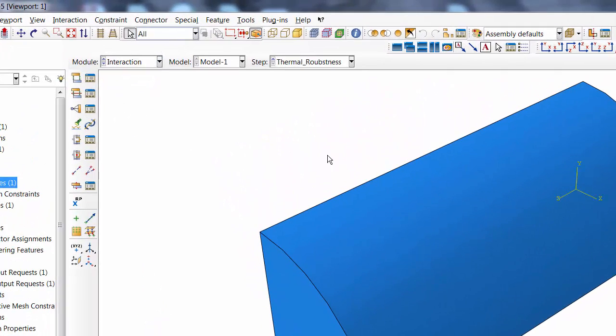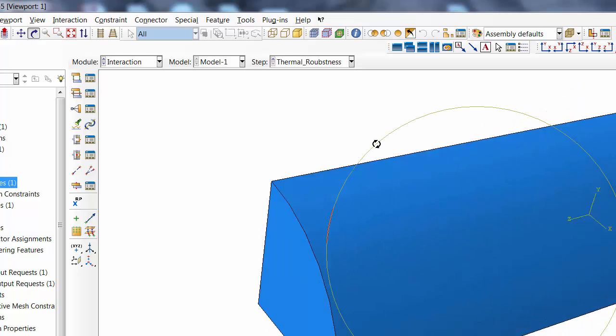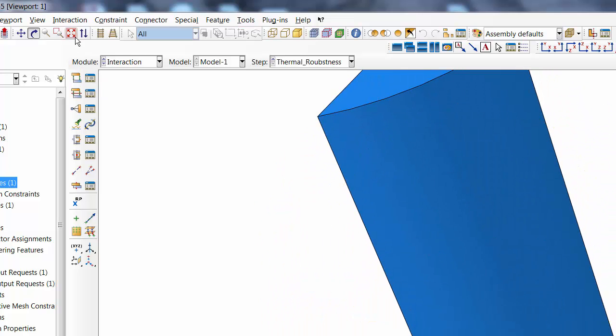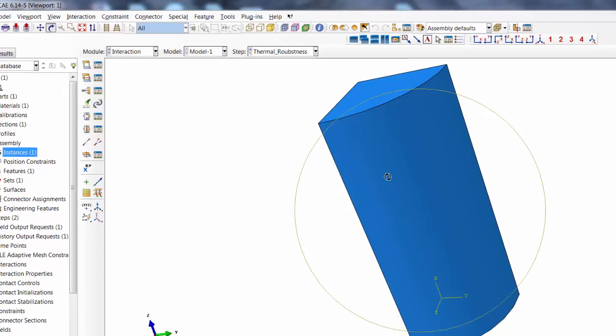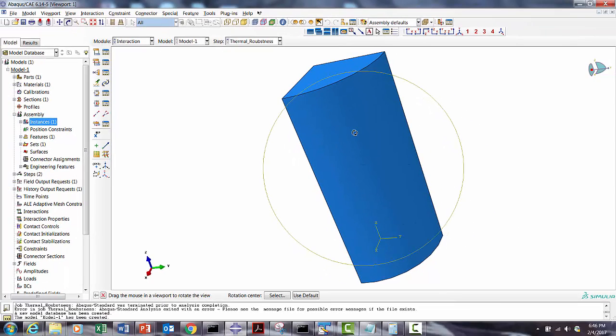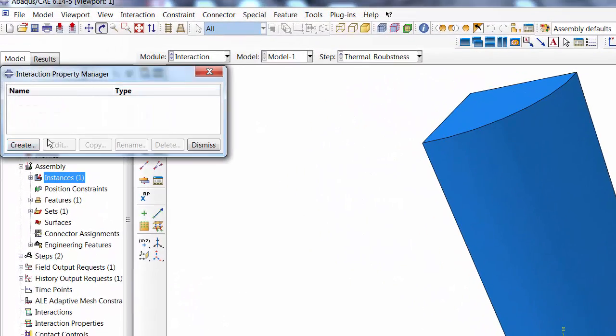Now what we are going to do, on the outer surface you have a film coefficient H. So your convection heat transfer is H A delta T. If you put a fan and blow the air, your H will be high. If it is natural convection, it will be on the lower side. But as temperature goes up, because of density difference, you get quite a high H in natural convection also.